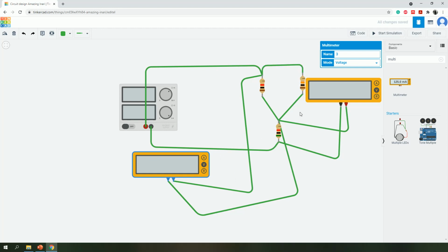We know that this was 16.9, the voltage that was dropped across this resistor, and the voltage supplied to this system is 20 volts. So the remainder has to be dropped right here. 3.1 was our guess. Let's see whether we have guessed it right. So it's pretty close. This is again the resolution of the meter.